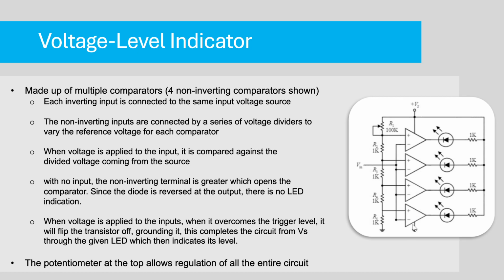So that's how, using that transistor and the combination of the 2 terminals, it will allow it to flow on this side, because obviously these are biased this way, from right to left. So it'll allow it to flow through that comparator to ground and complete the circuit. That's how this one, with the least amount of voltage being applied because it's being divided the most, will turn on first, and then this one, and then this one, and then eventually that one.